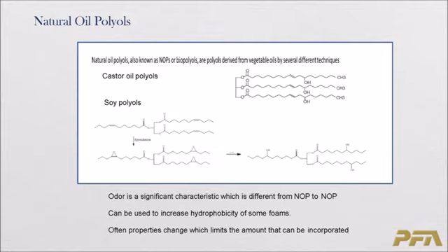And some of the things to be aware of with the soy polyols is potential odor concern, and that odor can vary from production process to production process. And also they tend to have a slightly acidic character to them, so that might affect reactivity.